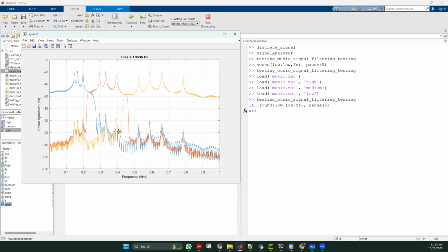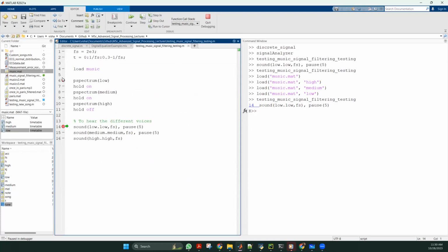Once you talk about the band pass one, it will have signal amplitudes only in the region between 230 up to 450. Therefore, the orange plot is slowly increasing and then decreasing. And the third plot, in yellow, has amplitude below 60 dB until it will have considerable amplitude after 450 Hertz. And it will have a function like this. So this is the plot of the filtered signals.